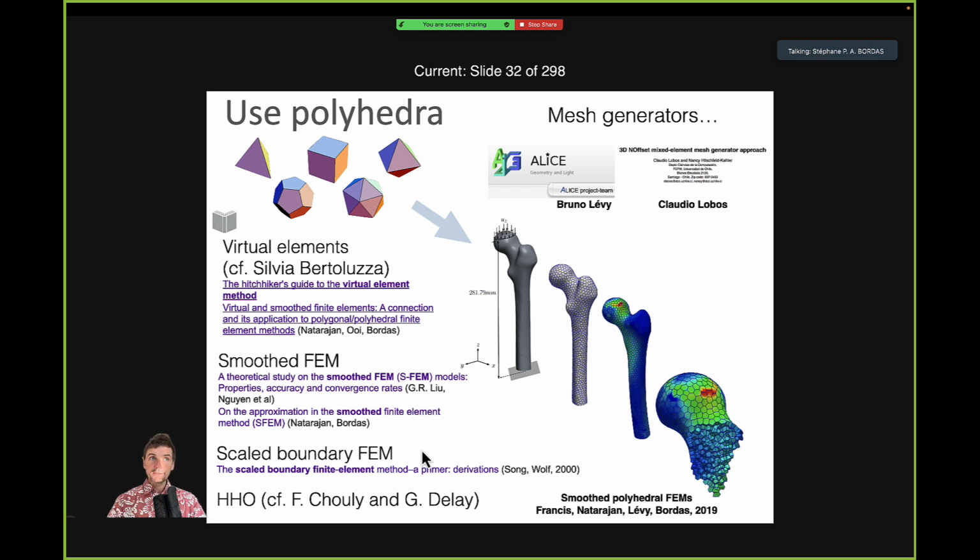There are, of course, difficulties due to finding the scaling center, which needs to be done in a convex hull. You cannot find a scaling center if you don't have a convex element. So, of course, you need to find ways around this. But of course, these things can be done, and the accuracy is remarkable. So for fracture mechanics, I have to say that this is the most accurate method I've seen. Even boundary elements, at times, for certain problems, do not compete with scaled boundary finite elements.